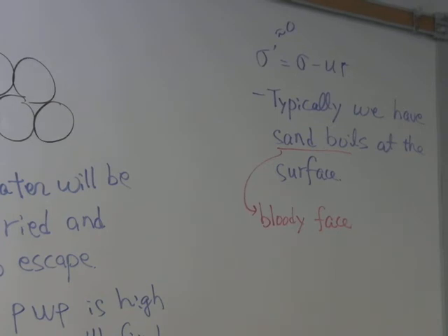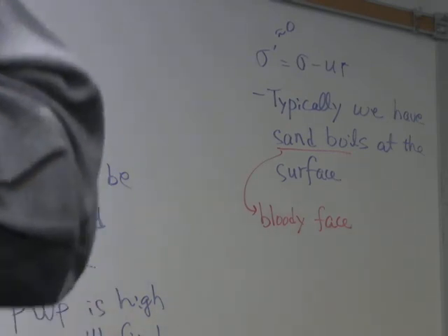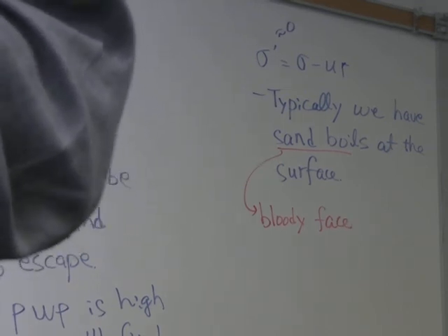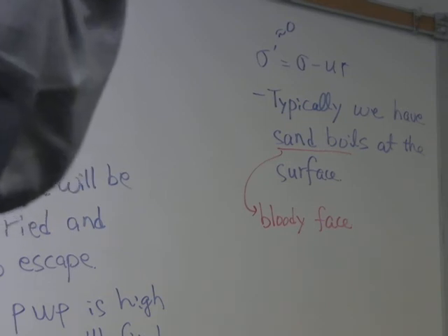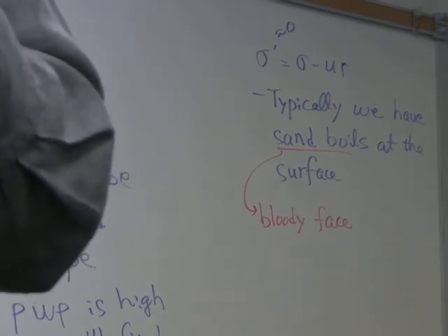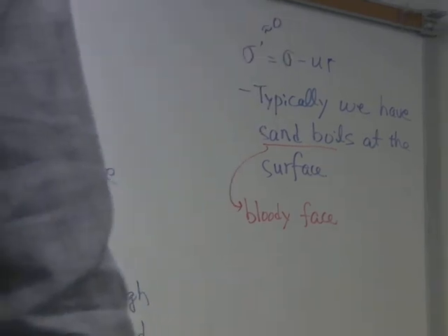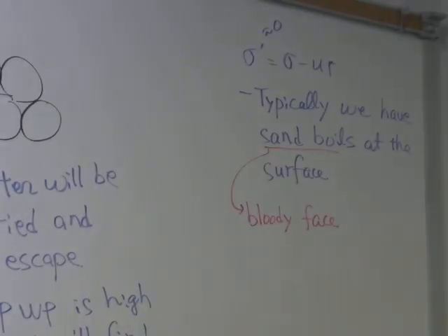Yeah, liquefaction itself means effective stress should be 0 or almost 0. But again, if let's say your effective stress drops down to 50% of the original effective stress, maybe we can say liquefaction magnitude is, let's say, 0.5 or whatever, but we don't use that terminology.